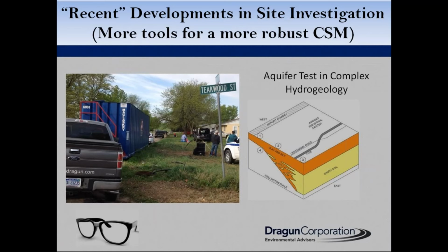And we've been working on the field work for about 2 years. As I mentioned, it's extremely complex. And in this conceptual site model, you can see we're working, in this photo, in this area here, where there's interbedded sand and clay. And we want to be able to determine how far the contamination has moved. We want to make sure we're measuring the contamination in the most permeable zones of sand so that we could get the worst case scenario.